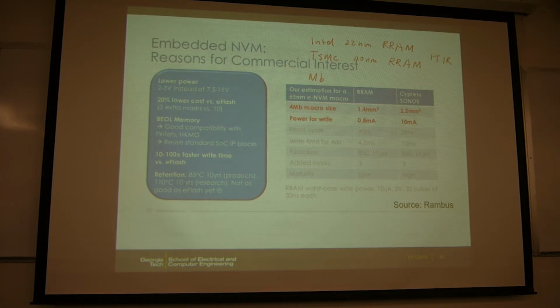So you need to have some barrier to prevent that. Especially silver is not used at all in the silicon process. It's very dangerous. So that's why I think they prefer the oxide, because those oxide materials are very compatible with today's CMOS fabrication. They use hafnium oxide, so it's the same as a high-K dielectric.